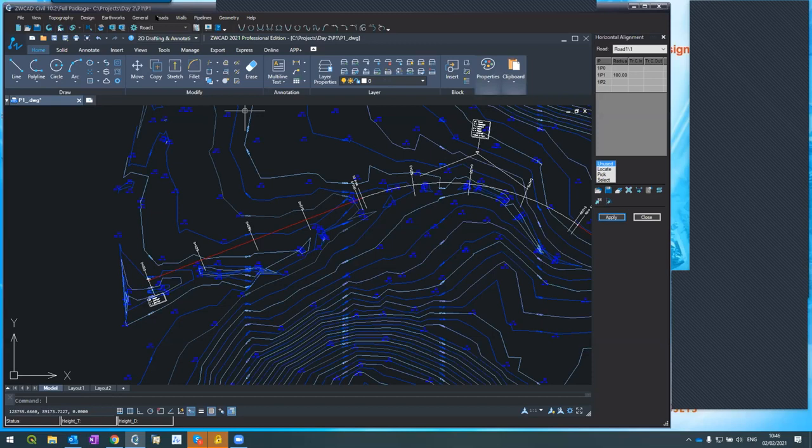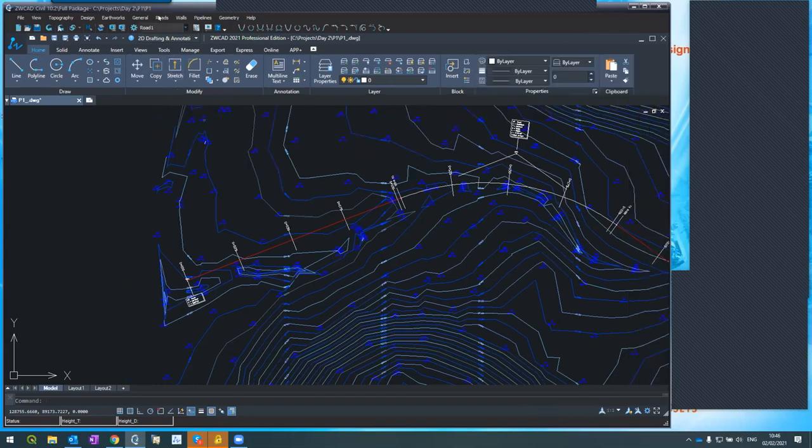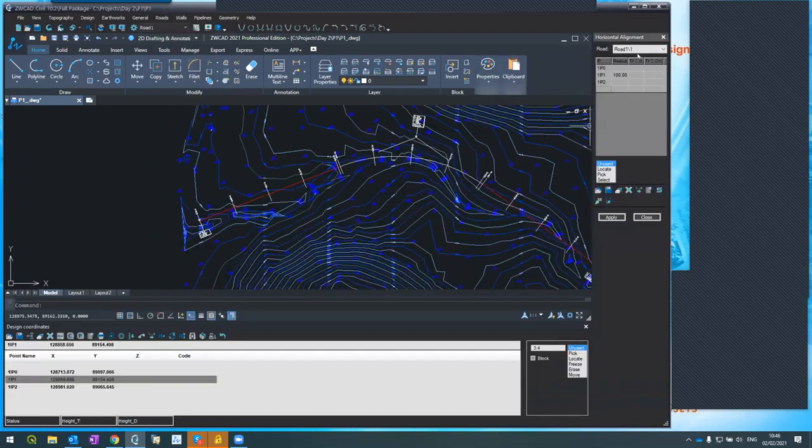First of all, let me define a new road. I'm going into roads list. And here there's a list. The default was only one road named road 1, which is the one that I used. I'm entering a second one named road 2 and press enter. And then okay. If I go again to the horizontal alignment, now on the top I can flip into road 2. Here now I am in road 2. I hope you got it. I created a new one. If I add road 3, then I can flip to road 2. I can go back again to my road 1, whichever I want to work on. Very simple.